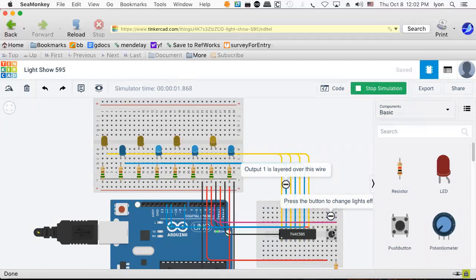And so this is very useful because if you can imagine, instead of lighting up LEDs, we stimulate the output of an R2R ladder, we can basically simulate an SPI DAC. So if we take these little LEDs and use them as inputs to our little SPI DAC, this enables us to avoid having to use 8 outputs.